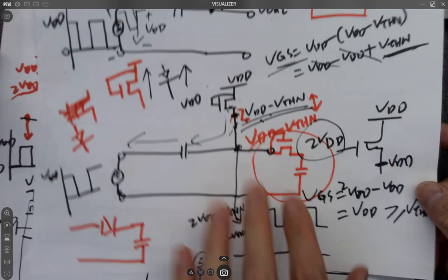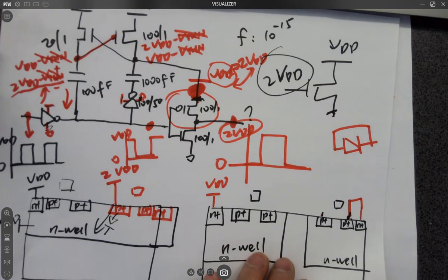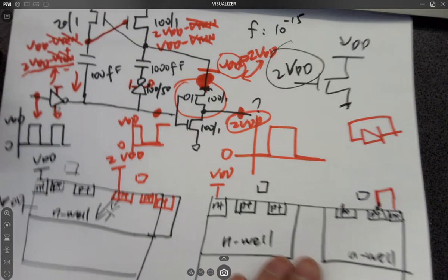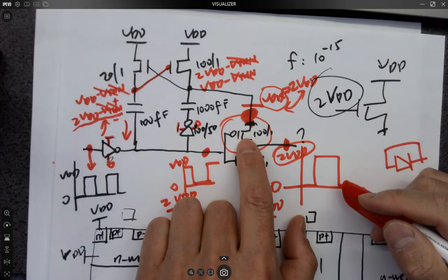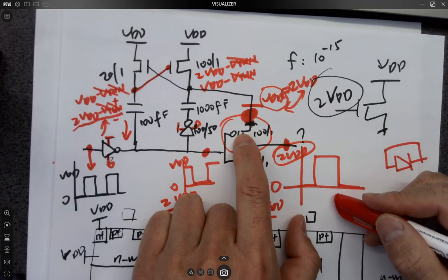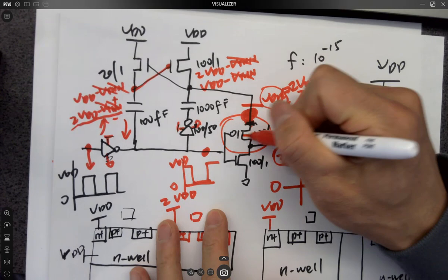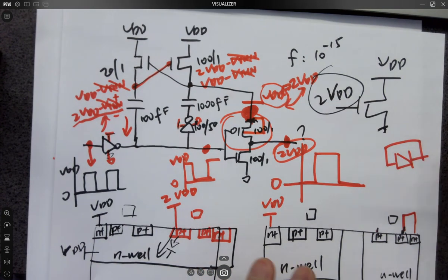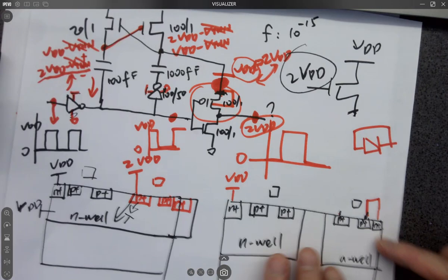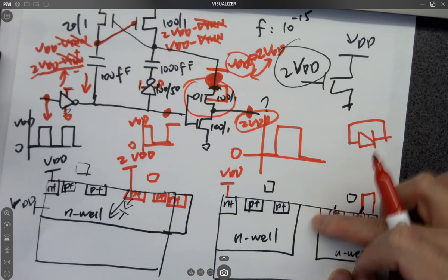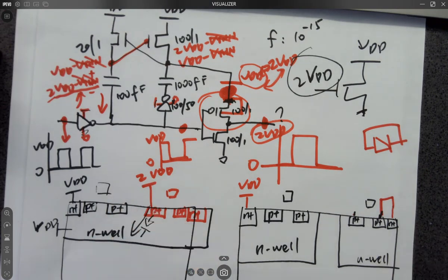However, here you short it to the source, but not VDD. You know what I mean? So in that case, you need to grab a 4-terminal PMOS device and short it here manually. You do this in the schematic, and you do the same in your layout like this, and separate the N-well. So they will pass LVS, they'll pass the well check.